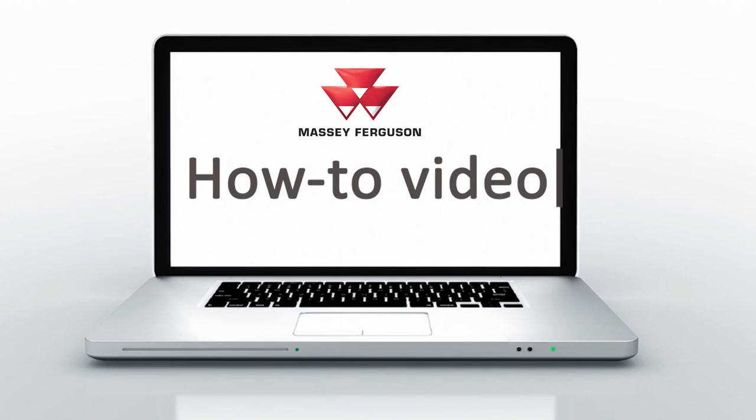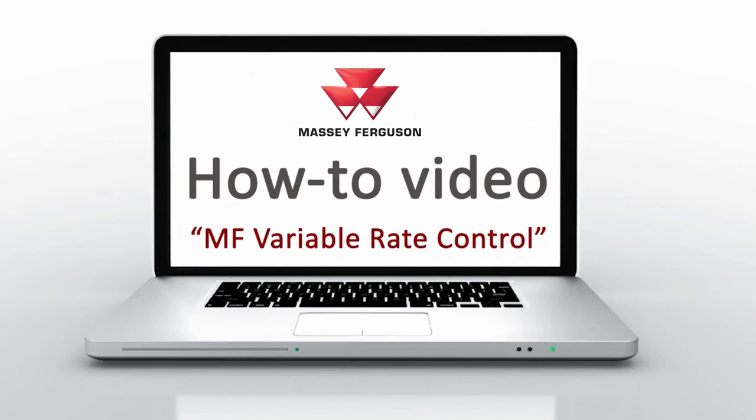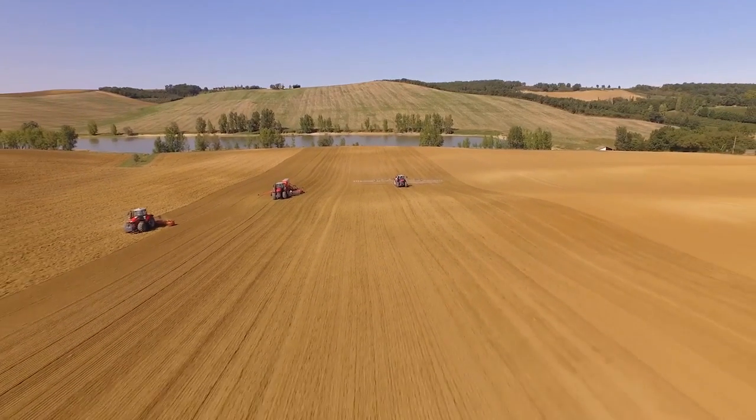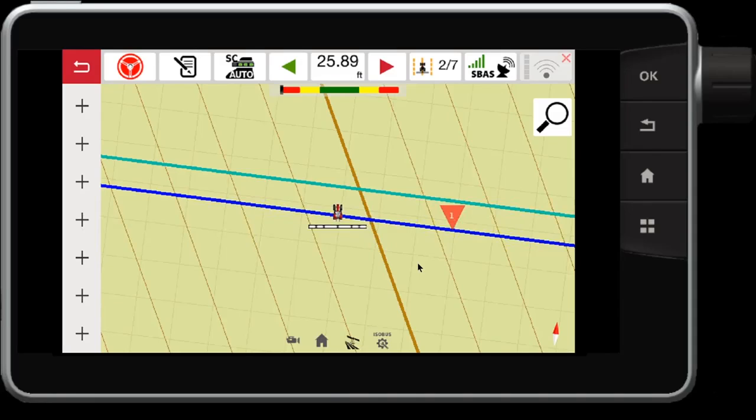Today I'm going to show you how to utilize a prescription map with the Fieldstar 5 or Datatronic 5 console by Massey Ferguson. Today I'm in a Massey 7700S with a Fieldstar 5 console. Prescriptions can be loaded into this console via USB or via cellular with TaskDock Pro.